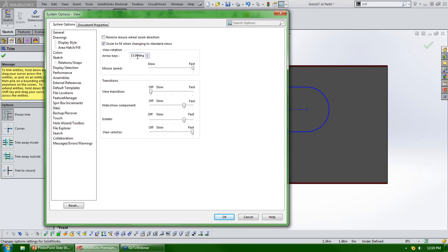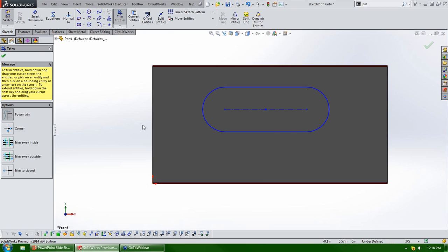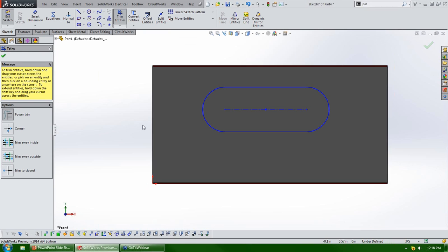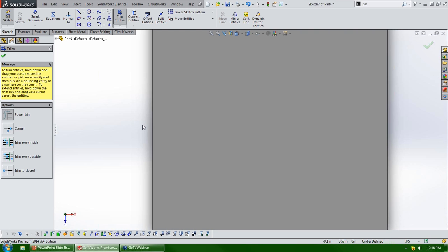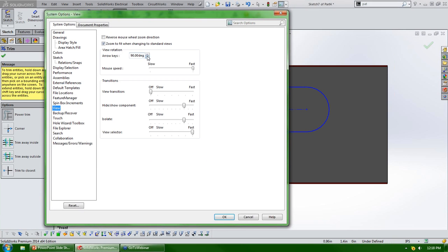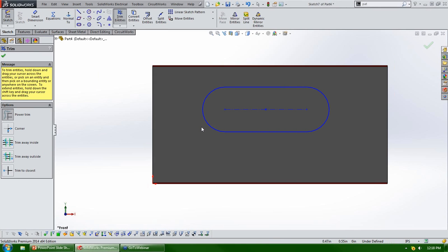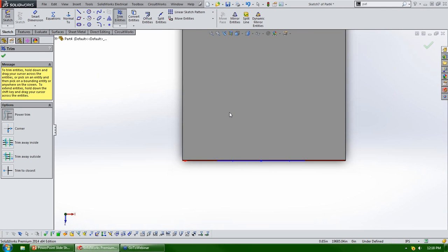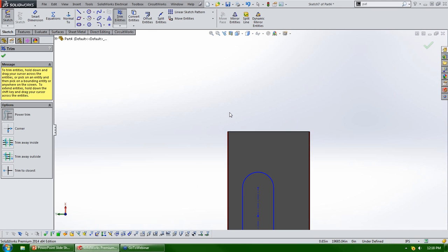You can also use your arrow keys for rotation. So if you're only working with boxes, you might want to set your arrow key to 90 degrees, and every time I hit the left arrow, my block is moving 90 degrees. Whereas if I change that to 45 degrees, you'll see that I'm only turning 45 degrees for that block.